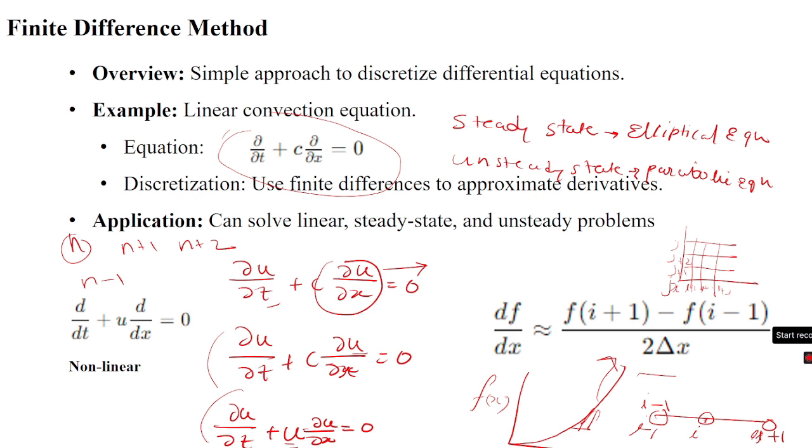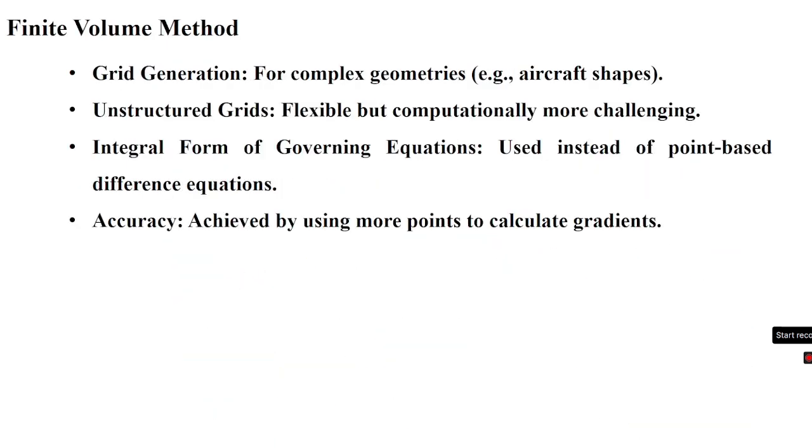So in the finite element method, accuracy is achieved through P refinement or H refinement. P refinement refers to increasing the order of the polynomials within each element, which enhances the solution accuracy by better capturing the gradient. H refinement involves adjusting the size of the element, where decreasing the element size can improve the solution precision. So together these refinements help achieve greater accuracy in simulation.